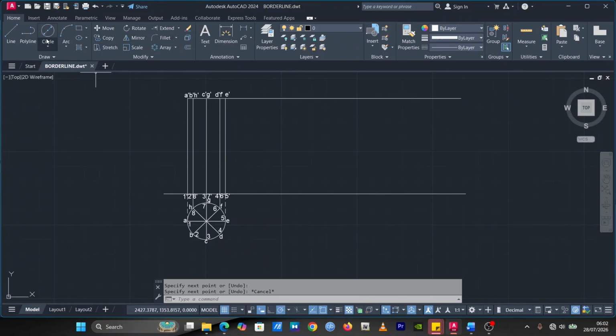So we first pick our offset tool. We offset this line. First, make sure you draw a line, maybe maximum of 10 millimeters before you start with your drawing for the base. So let's say maximum 10 millimeters. So we can call here 1. This is our 1, and here will be A. Okay, so when we are done, let's start offsetting. Now we know that after dividing 79 by 8, we are going to have 9.8. So meaning each length distance is going to be 9.8. So we have 9.8 over here. So we do that 8 times.